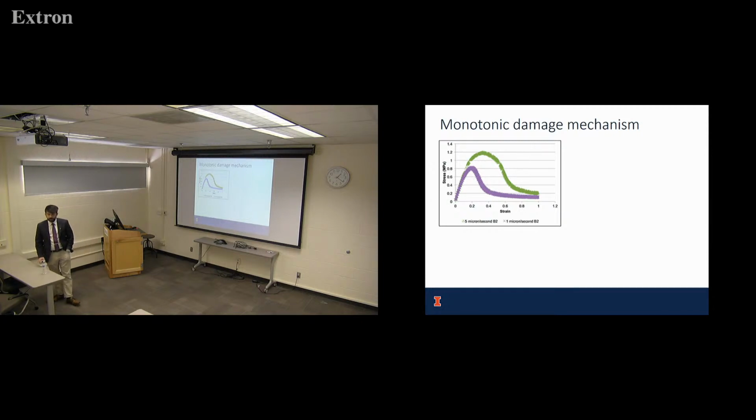Was it modified as well? We don't know, so these were just obtained from the producer and we didn't ask. It was PG 64, so we think no, but in Texas you see a lot of blending too, so it could very well have been polymer modified, and that level of elasticity does make you think polymer modified, right? It could be a 70 that was blended with a 58 to reach 64. That's common in Texas. But if it was a neat 64, then for sure it wasn't modified. That's generally not modified, but we don't know because, like I said, binder is a black box, especially in Texas. We don't have any idea what the modifiers are.